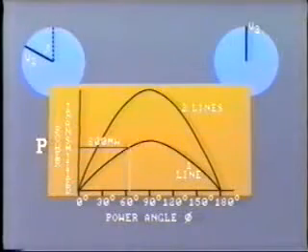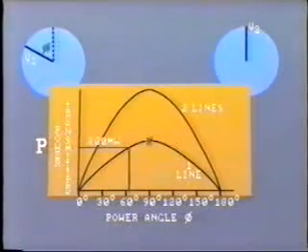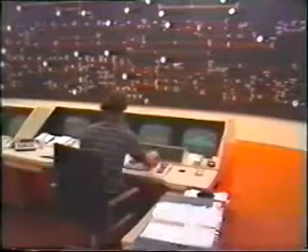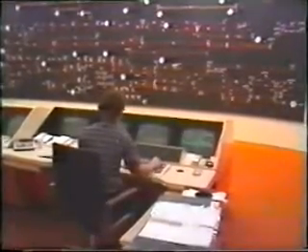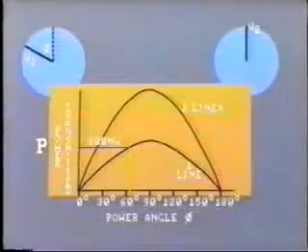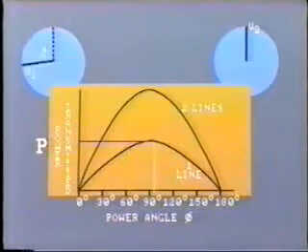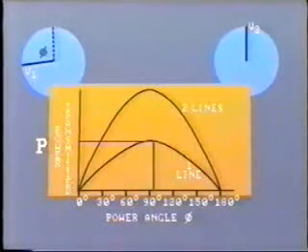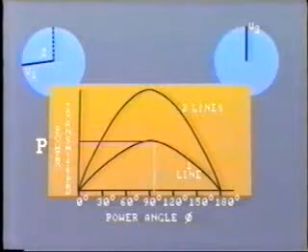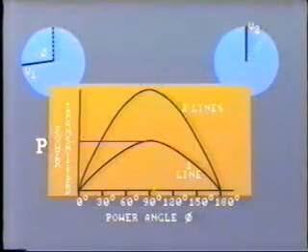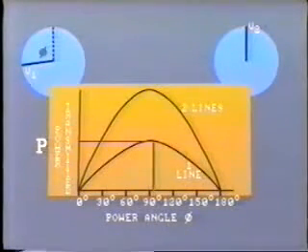With this large angular displacement, we are already approaching the stability limit of the line. In order to avoid this, the system operator would probably reduce the load transfer before switching the line out of service. But this may not be possible due to the loading around the system. Now, in this precarious situation, any disturbance on the power system, say a loss of load or a loss of power generation, may cause the voltage at V1 to advance further, or perhaps the voltage at V2 to lag such that the load angle between them exceeds 90 degrees.